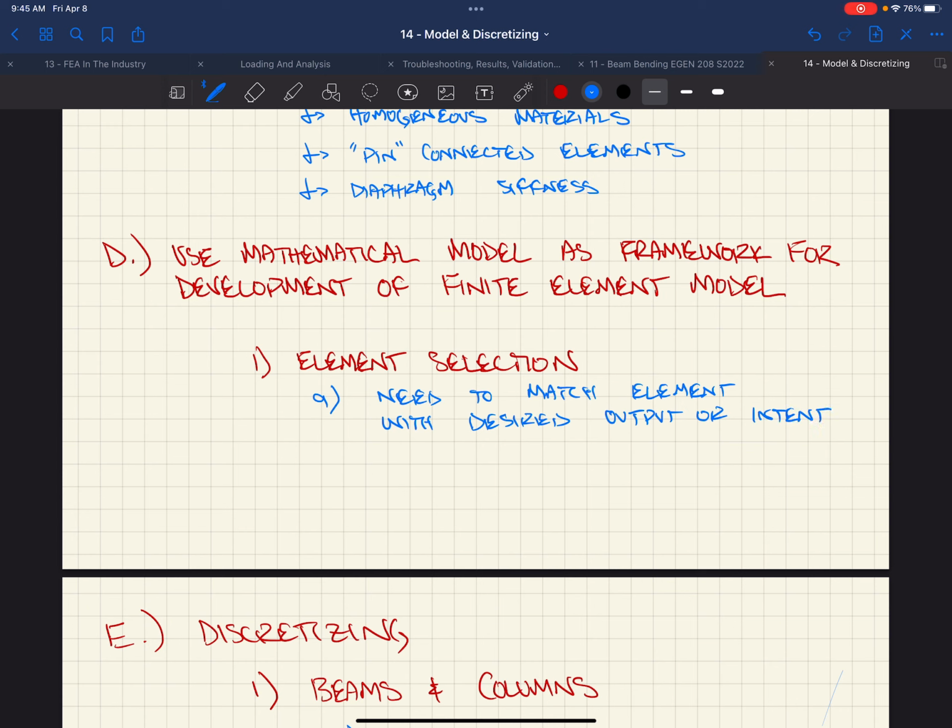Right? In this case, it'd be like, do we use a plate versus an area? Do we care about stiffness? If we care about stiffness of that element, maybe we want to use a plate. If we're just trying to push our load across our model and just load elements, maybe we ignore the diaphragm altogether. We're talking about this again, and we make those assumptions using an area. Maybe we just use an area, not a plate. Right?